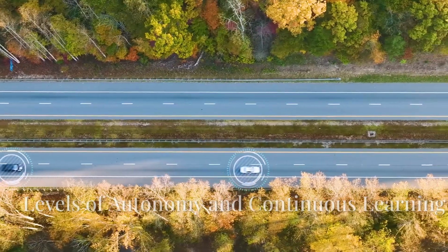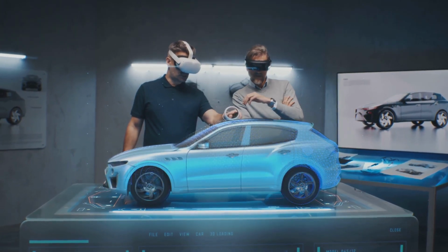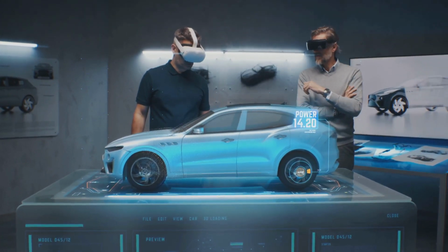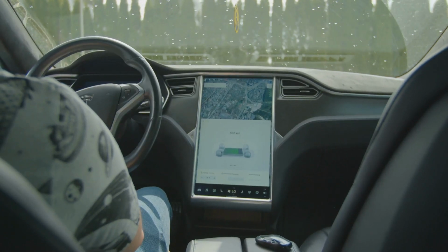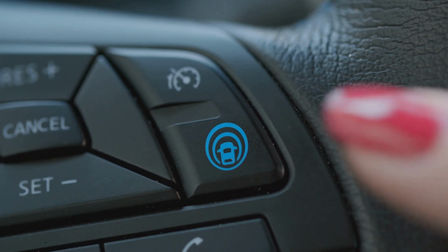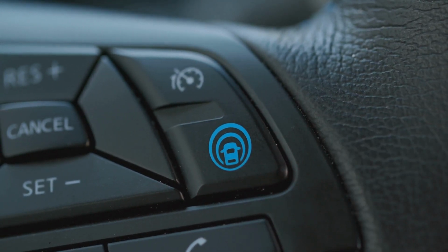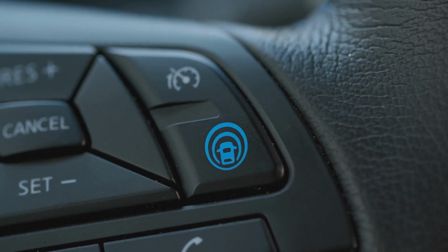Levels of autonomy. ADAS is often associated with levels of driving automation defined by the SAE, or Society of Automotive Engineers. These levels range from 0, which is no automation, to 5, which is full automation. Most ADAS features today belong to Level 2 automation, partial automation, where the system assists with driving but requires the driver to remain engaged and ready to take control.